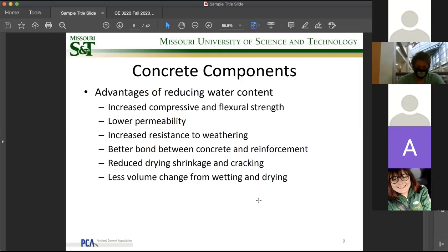Why? Because the harder or pastier the concrete is, it creates a flow layer between the concrete and the tube, preventing the concrete from going up, no matter how much pump pressure you add to that process, okay? So not only do you need to remember the advantages of reducing water, but also keep in mind that a lower water ratio can cause rheology problems during your working of the concrete itself, okay? So the pros and cons, okay?